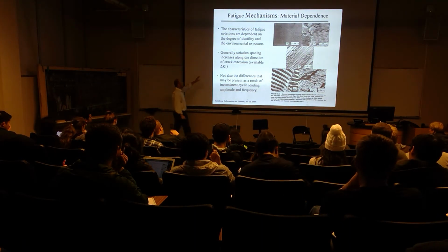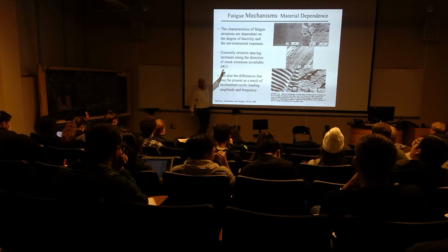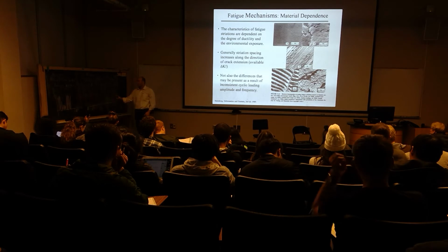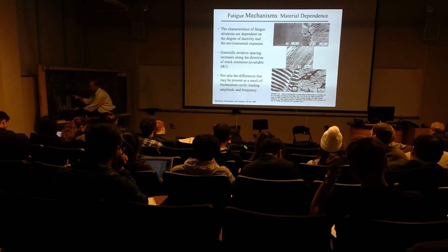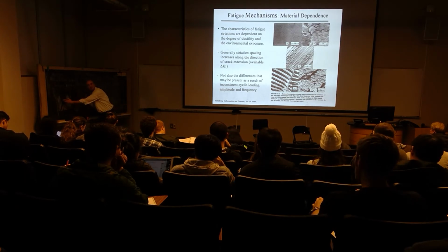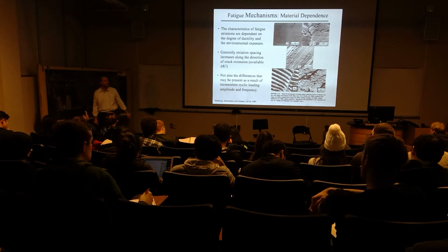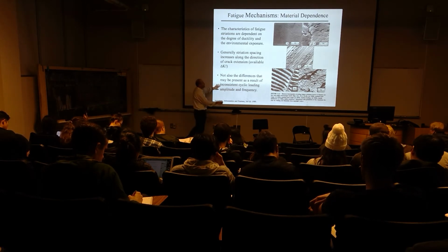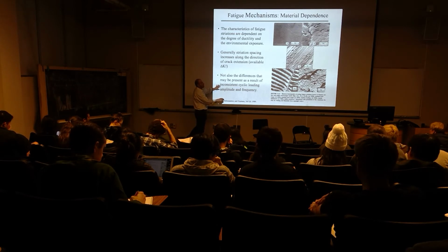So spacing, we know that spacing is a function of delta K, and delta K is a function of delta S, the stress range. So anytime that I think that the stress range increases, I should see the spacing increase in dimension as well, right? And then we might see that the inconsistency in load cycling tells us something about how that crack grew.